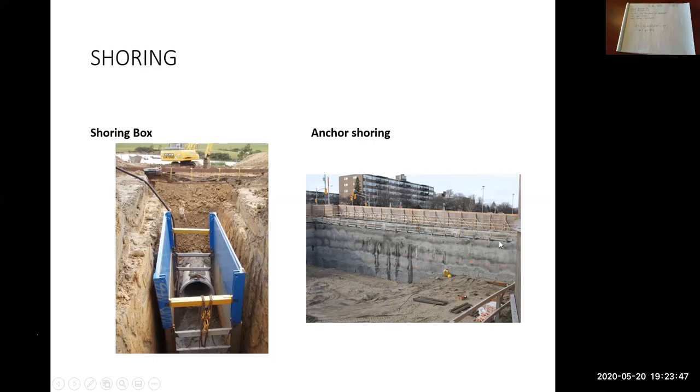So you can see there's a handrail system here. So there's a job site fabricated handrail, so people can walk along here so they can't fall into the excavation. Then there's this hoarding, as it's called, on the top. So on the other side of this is where the public is, so they can't see in, is what that's for. Again, it keeps the public out. It's quite a bit higher than the handrail. This is probably at least 1.8 meters tall, maybe 2.4 meters or 8 feet. So it's fairly tall.